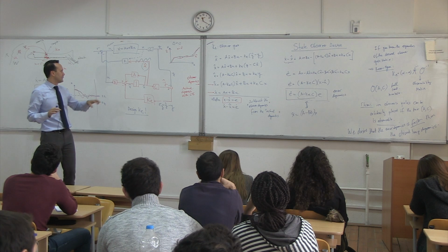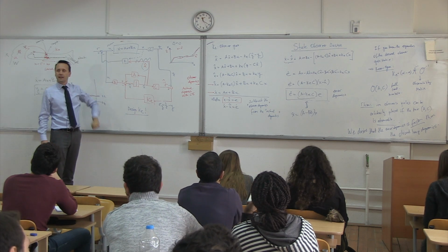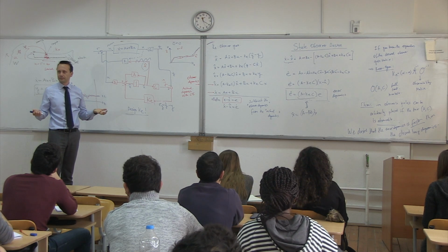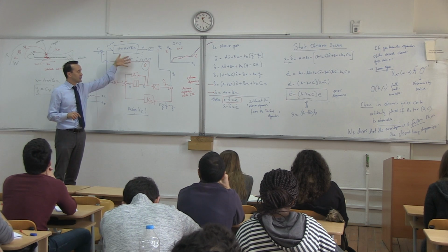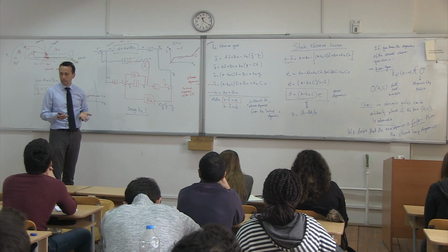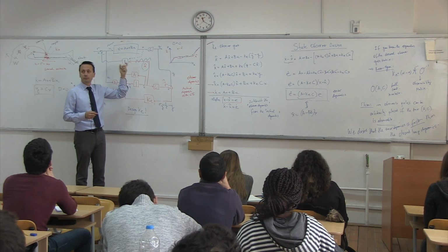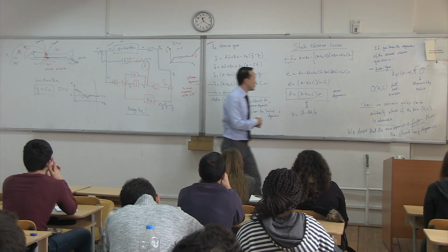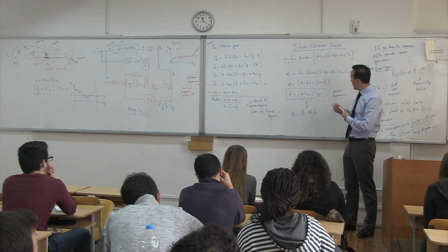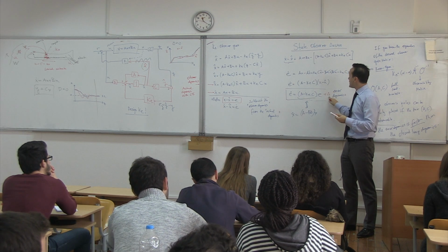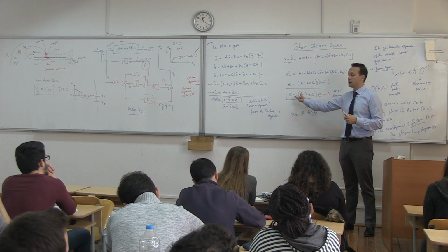But you need to understand that this observer dynamics is really valid only at this equilibrium point again. Okay? So if you're a little bit away from the equilibrium point, then this will not match this one anymore. Okay? And another thing is you might not be having the perfect measurements. So in other words, the aerodynamics doesn't really look like that all the time. It always has some input to the aerodynamics. And this is like an input to the aerodynamics.